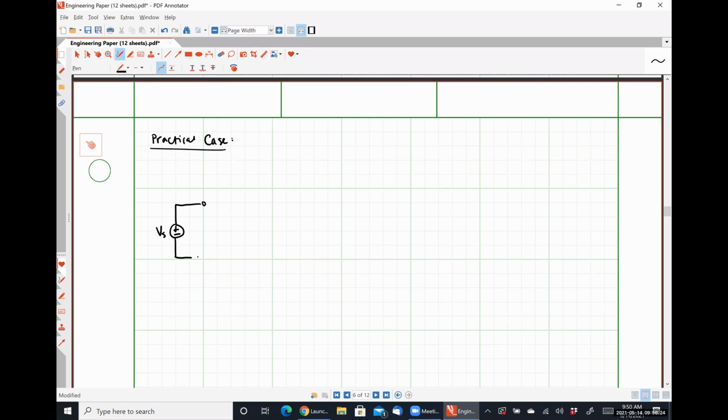we have our signal voltage Vs, but we may have some finite signal resistance, which I'm going to call Rs. This is the S terminal, this is the S prime terminal. If we look in from here, we see RIF. If we look in from here, we see RIN, which is the closed loop input resistance, excluding that signal resistance. I just want to be clear about that.